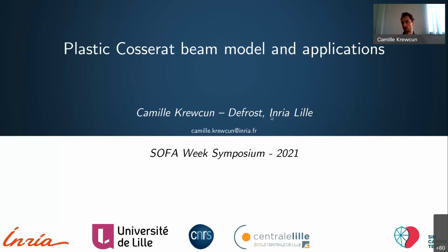But if you're using something that has been manufactured and stored in sealed packaging or something like this, you could always have some kind of pre-deformed shape before using it. And then it's hard to say what type of plastic deformation you want to simulate to reproduce that, because if you don't have the history of deformation that your material underwent, it's hard to say which type of deformation you should reproduce in the simulation before simulating the real application you're interested in.